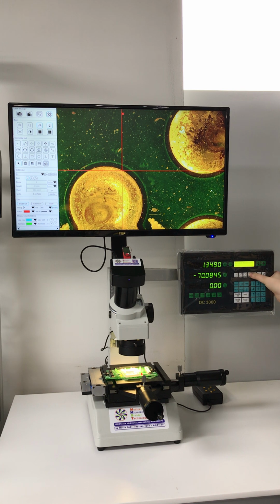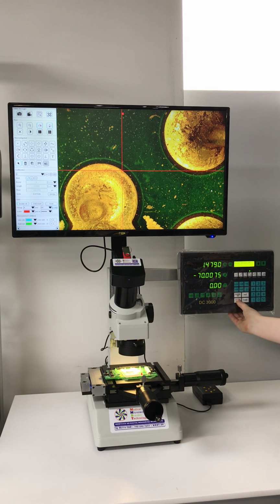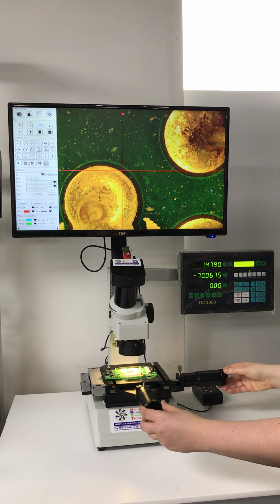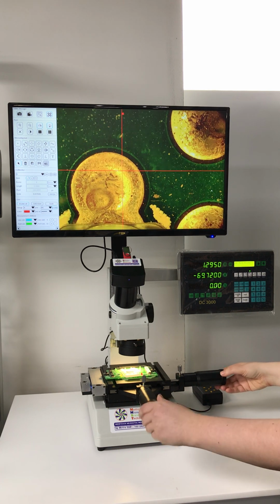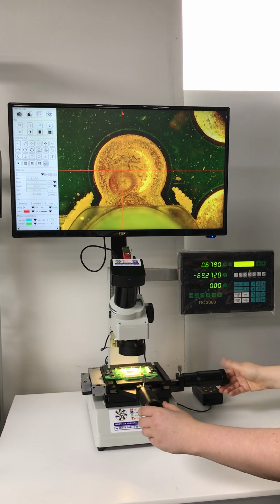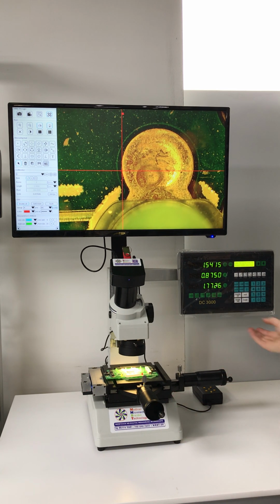To do distance, press this distance button. Now line up your part. Press enter. And do one more point and press enter. So it'll give me my X, my Y point, and the distance. More. And if there's any more features, it'll press more.